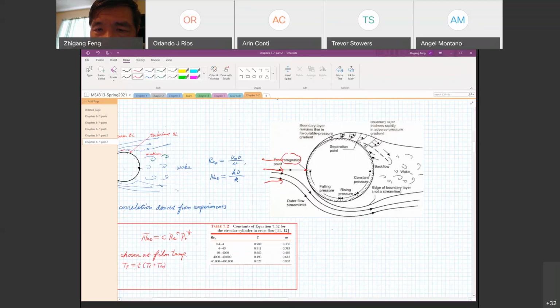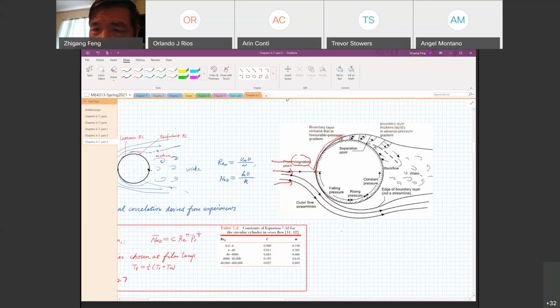And then you actually have a fairly thin boundary layer. It's called the laminar boundary layer. It starts with a very thin laminar boundary layer. And at a certain point, the flow will start to separate, which means you will see the backflow. You will have an adverse pressure gradient, so partial P over partial x, where x is the coordinate along the surface, becomes positive, and the flow is pushed backward.